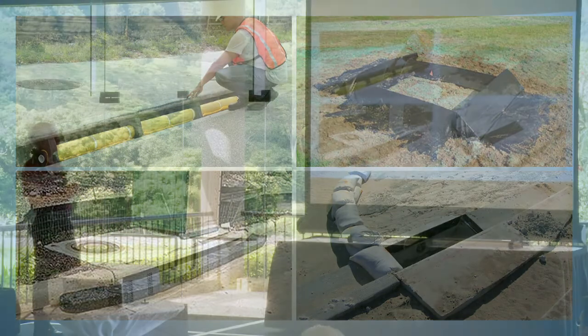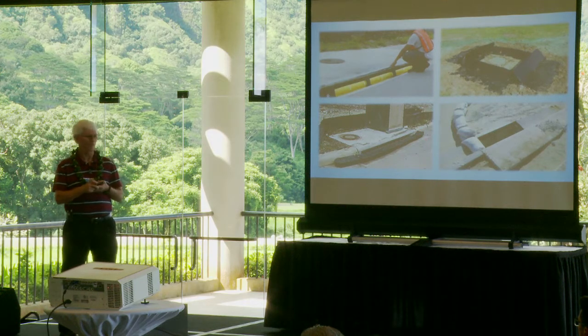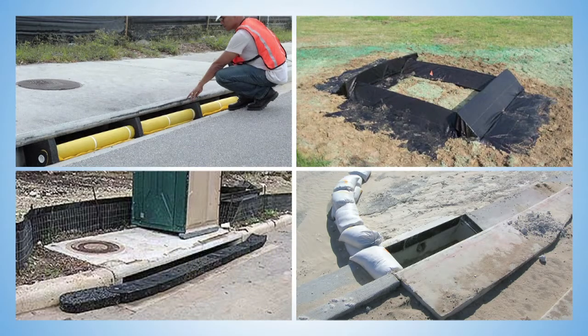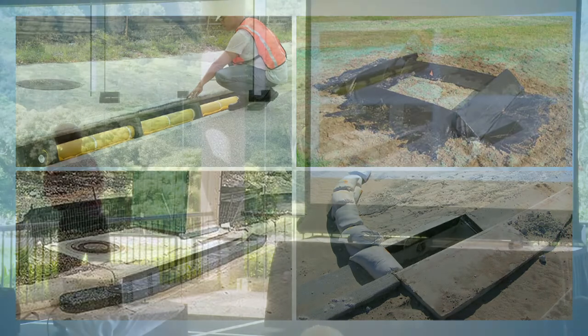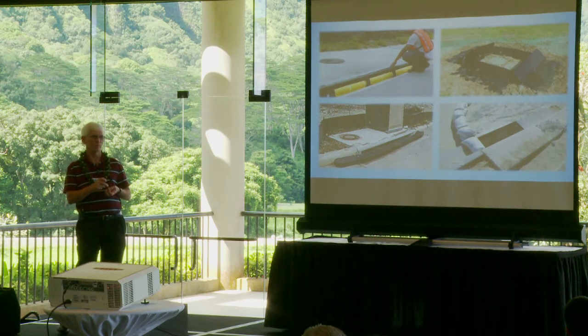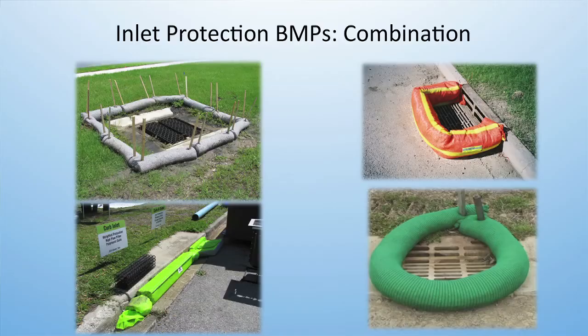This one is actually a granite inside of a very strong plastic netting that's strong enough to survive vehicles running over it, but again, it will stay in place and not blow out, and positioned the way it is, it allows overflow. Even something as simple as rock bags, if you do them right, they're capable of performing well, but pretty much have a limited life. The bags don't last typically more than a few months before the UV breaks them down, so they're not really reusable in any lengthy period of time.